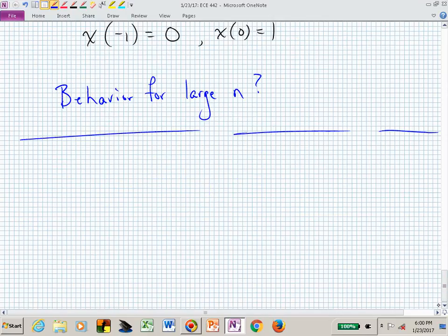So let's talk about a settling time. That means that we can't be dealing with poles on the unit circle, -1, or any particular complex value that might fall right on that unit circle, or anything outside the unit circle.